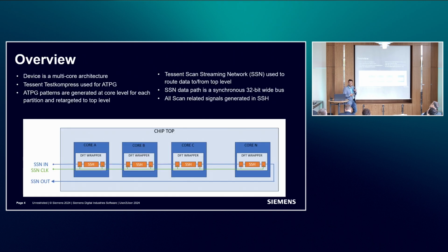Okay, here's the overview of the system. The device of interest here features both multi-core and multi-partition configurations, which are almost a standard in most SoC designs now. SSN and EDT are utilized for logic test purposes here.